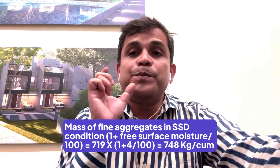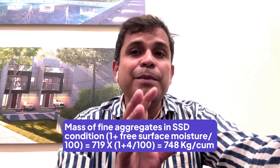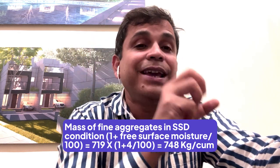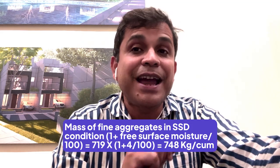So to keep our mix proportion the same, according to the 719 kgs, we need to take 748 kgs of sand to get the 719 kgs of sand into the mix, and the remaining 29 kgs is the water. So these 29 kgs will be added into the water in the mix.